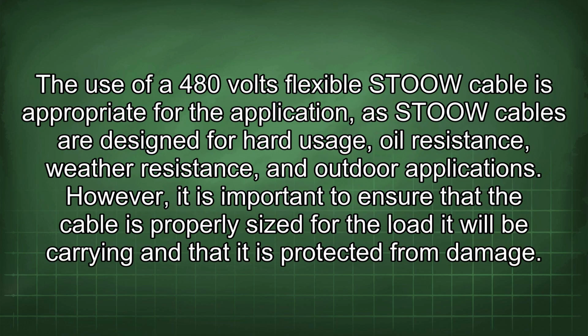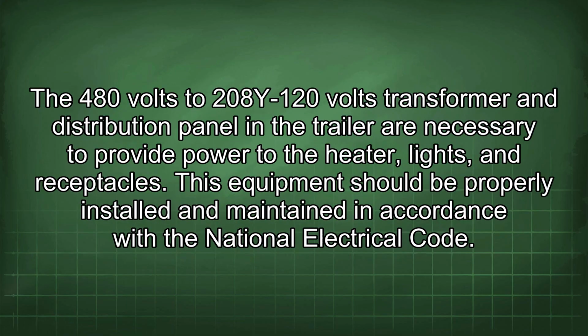The use of a 480 volts flexible steel cable is appropriate for the application, as steel cables are designed for hard usage, oil resistance, weather resistance, and outdoor applications. However, it is important to ensure that the cable is properly sized for the load it will be carrying and that it is protected from damage. The 480 volts to 208/120 volts transformer and distribution panel in the trailer are necessary to provide power to the heater, lights, and receptacles. This equipment should be properly installed and maintained in accordance with the National Electrical Code.